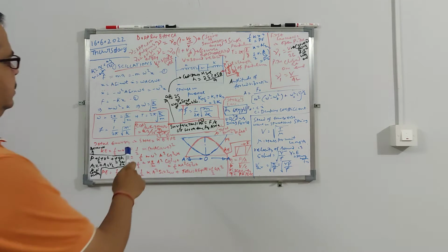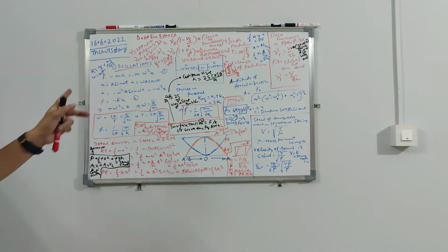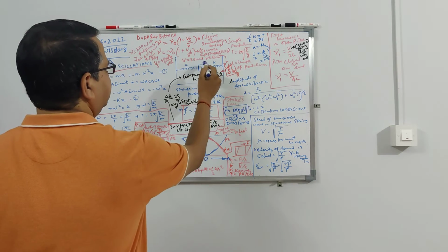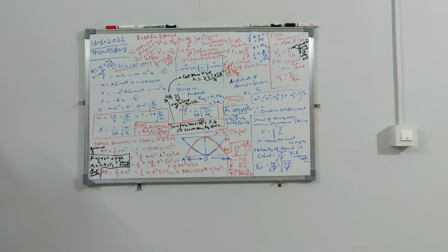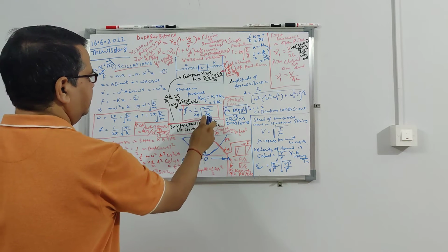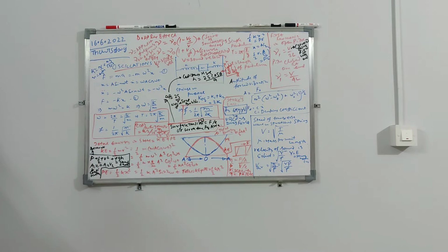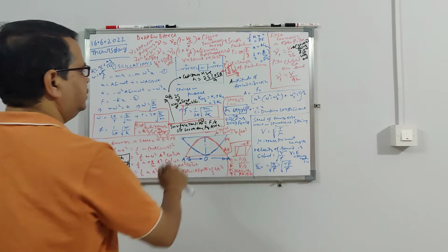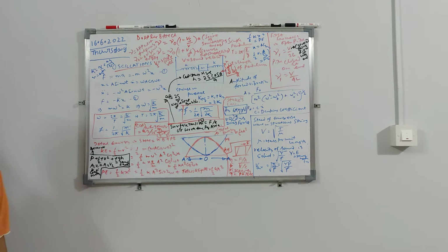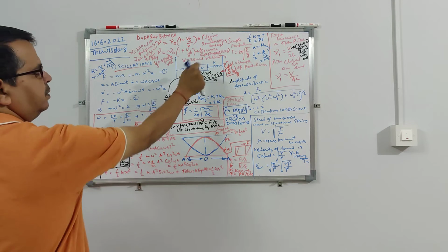Then there is this spring mass system in series. If you see something like this, it is series. Sorry, something like this is parallel. This parallel is the same as resistors in series. So your effective stiffness, K equivalent, for springs in parallel, like resistors in series, is K1 plus K2. Here the displacement remains the same.